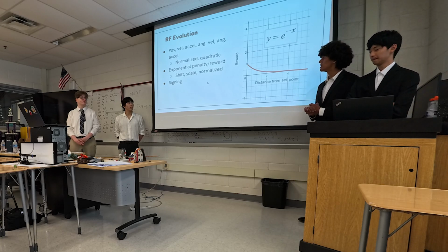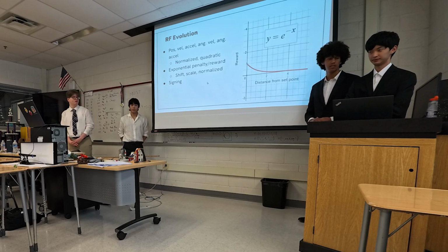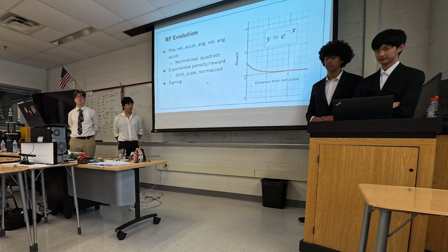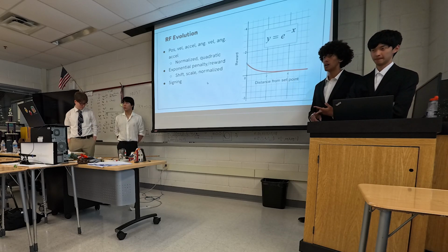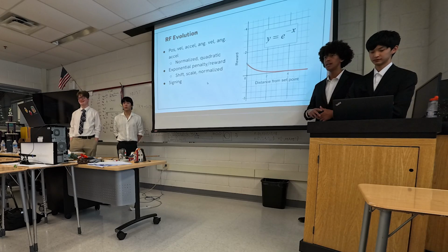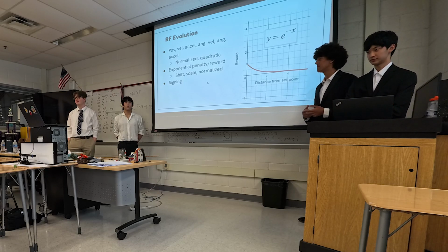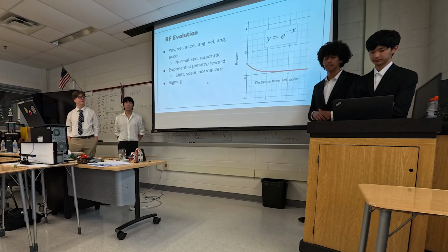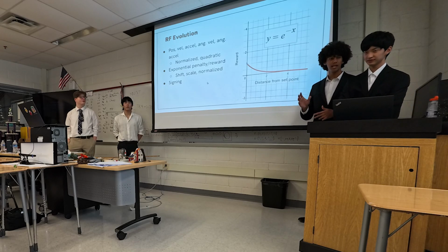Some of the things that we attempted during the initial stages of our project, when we were simply modeling this system on our computers through a simulation, were playing around with different parameters that we used with our reward function. We took different parameters from our state vector, including the position of the ball, the velocity of the ball, the acceleration, and then the angular velocity and angular acceleration of the beam, and used different combinations of these parameters in order to try to formulate our own creative and effective reward function to approximate what is a desirable state for the environment. Whenever we used these combinations of parameters, what we always did was we normalized them and we squared them.